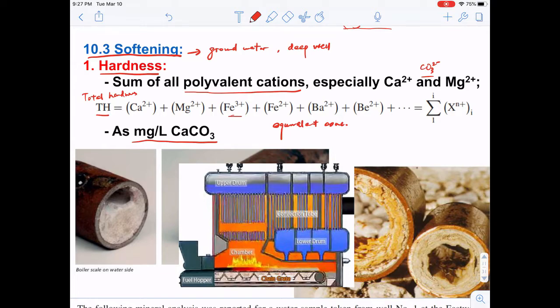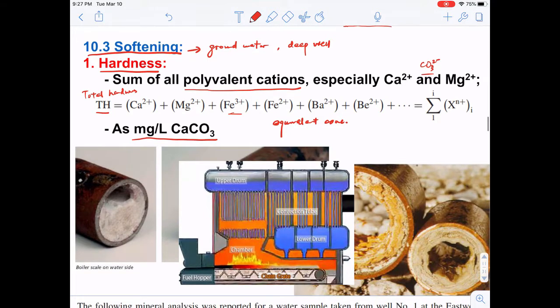As you can imagine, if we are pushing the same amount of water through, the smaller cross-section area means the velocity of the water will become much higher, and a higher velocity means a much higher pressure drop. So the pumping power has to be much higher in order to obtain the same amount of water. This can affect how residential people can use their water.